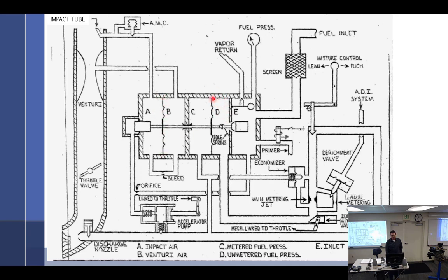All right, what happens if, and I'm not going to write all this down, so you have to write on your own, what happens if this diaphragm ruptures? The poppet would want to open as far as it can. Why would the poppet open all that it can? Yeah, there's nothing opposing it.